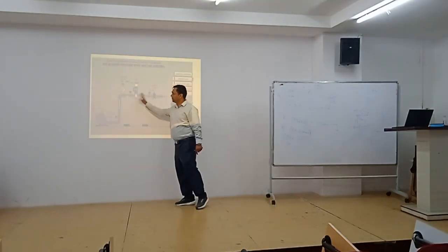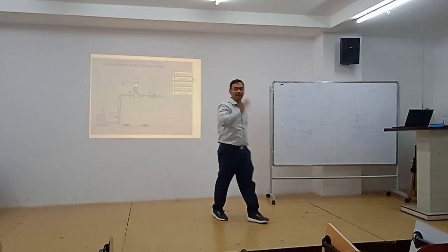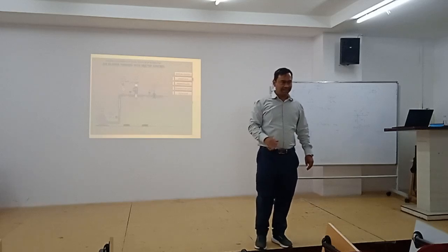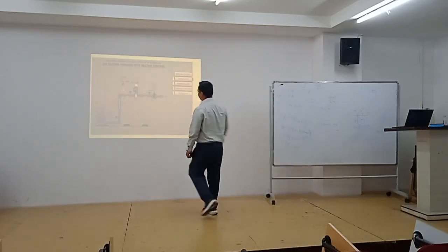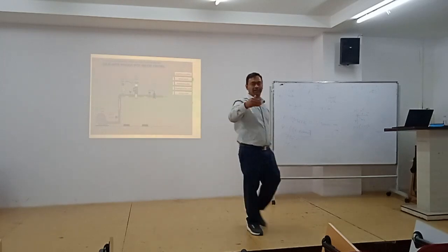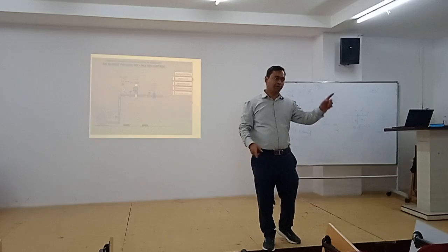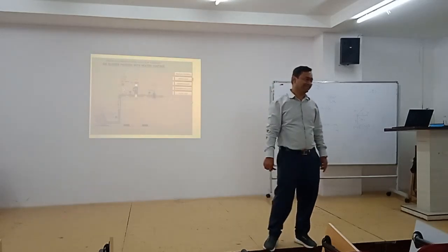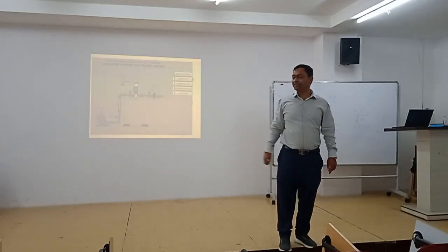So when we turn on the pump fully, it's going to give us a flow of 100 kg per hour. Now, if you operate this hand operated valve, you can change the flow as per your requirement. But the problem here is, in all cases, your motor will take the same power.